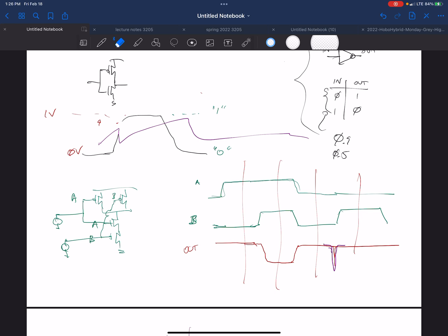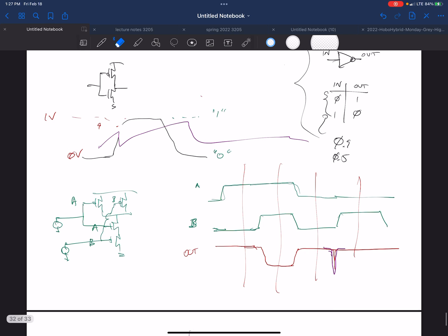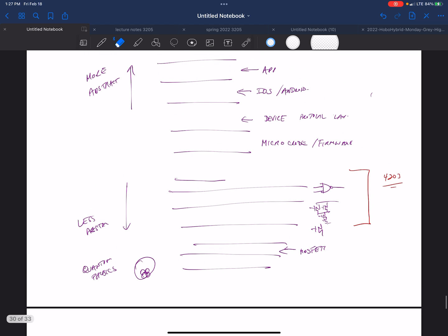And the other place where it happens, your chip comes back, and guess what? Your chip doesn't work. It blew up. Now you might want to jump down 3 degrees of abstraction and look at your device and go, ooh, I didn't do a good job of designing the electrostatic discharge circuitry on that output. It's blowing up as soon as somebody touches it. Now I got to go debug a MOS transistor. Okay, so that does happen. Sometimes in debug, things open up, but when you're doing design, you're usually cycling back and forth.